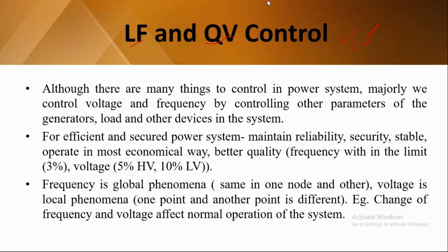Right. I will tell you an example for reliability. If you observe the three-phase transmission line system, it is a double circuit, a three-phase double circuit. What is the main intention of a double circuit? Suppose in the event of failure or repair of one of the transmission lines, we can use the other transmission line as a backup. So without any interruption in the power supply, it makes the transmission line reliable. So that is called reliability. It means that if there is no disturbance, it makes reliability.